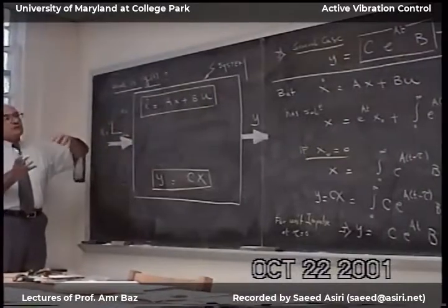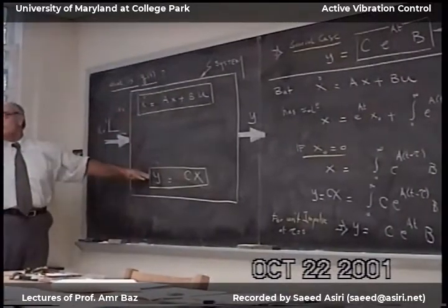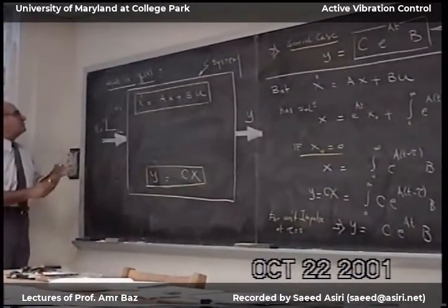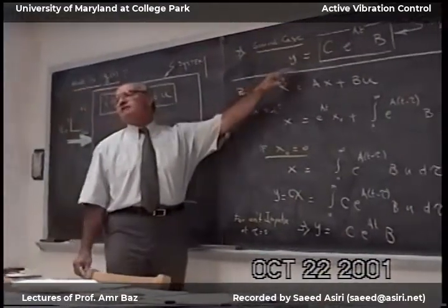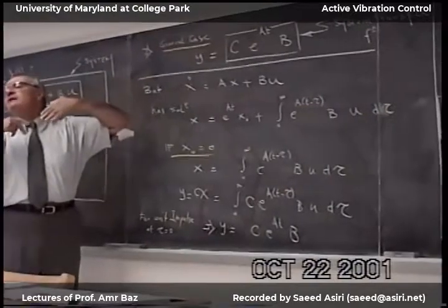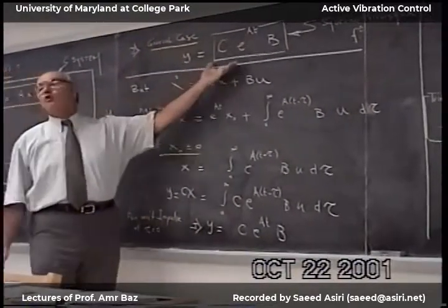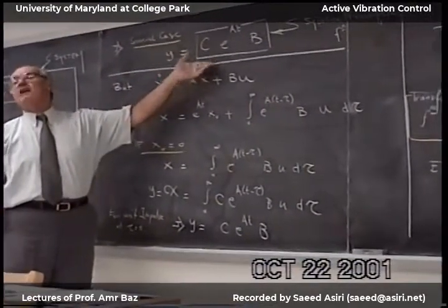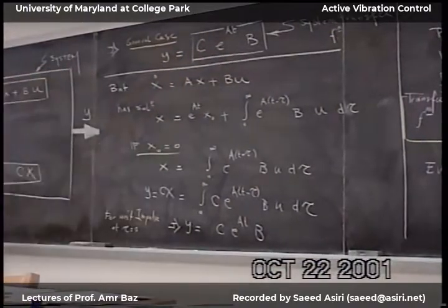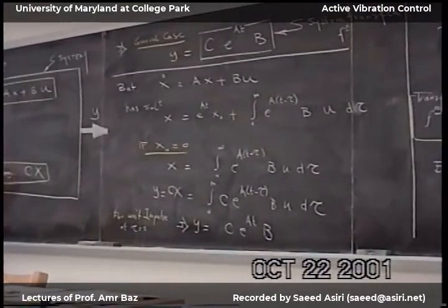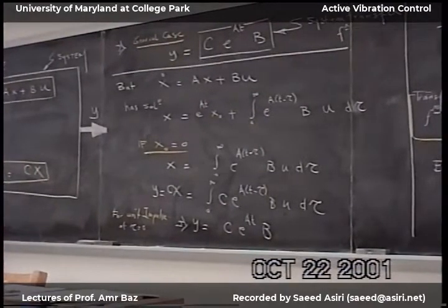I combine these two to get the transfer function of the system. We showed that if I put a unit impulse here, what I measure out here is nothing but the system transfer function. And in system identification, that's all we need to identify the C, B, and A. And once we have the C, A, and B, then I have everything about the system dynamics.